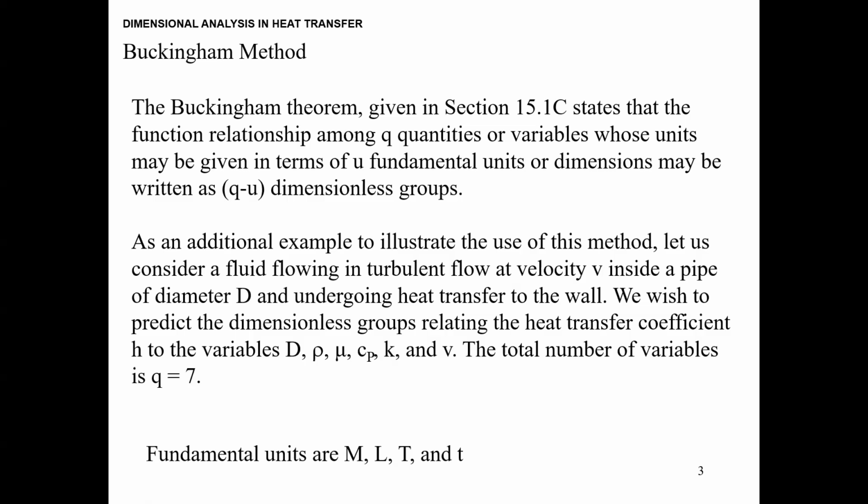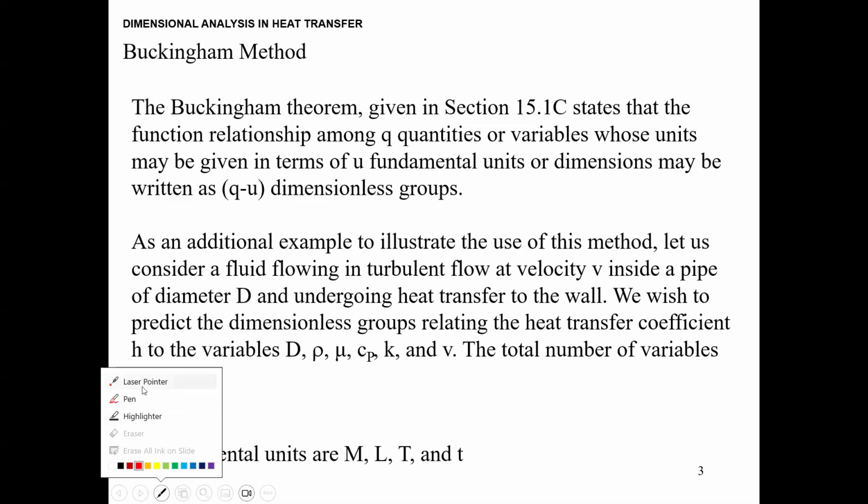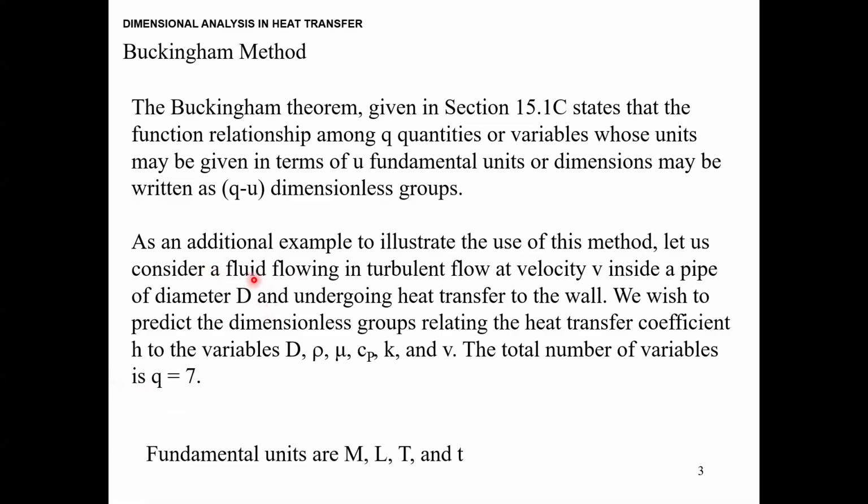And with this formula of q minus u, you will know how many dimensionless groups are actually involved in that case. All right, so as an example, let's consider fluid flowing. Okay, let me get the laser pointer. Let's consider a fluid flowing in turbulent flow at velocity v. So v is one of the variables or quantities inside a pipe of diameter d. So d is another variable, and heat transfer is also happening through the wall.